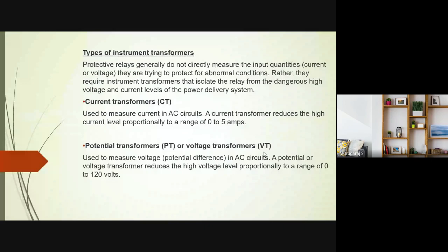Now, how do these numerical relays operate? In a power system, there are 110 kV systems, 132 kV systems, 33 kV systems, 11 kV systems, and 415 volt systems. But numerical relays are the same. Then how do you give the inputs to the relay? Can someone confirm, please: can the same numerical relay be used for an 11 kV panel and 415 volt low voltage panels as well?